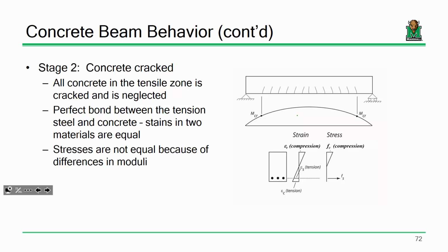Now, that doesn't mean that the beam's going in the river. There is a reason why the beam can still hold up additional load, and that's because we put something in the beam that can handle those additional tensile stresses. And what is that? Rebar. We put some reinforcement in the tensile region. So, hence the principle of reinforced concrete design.